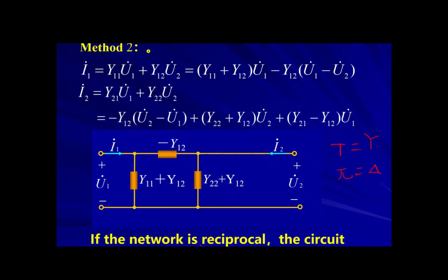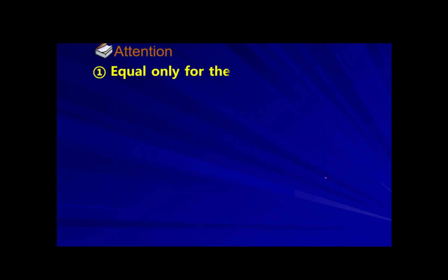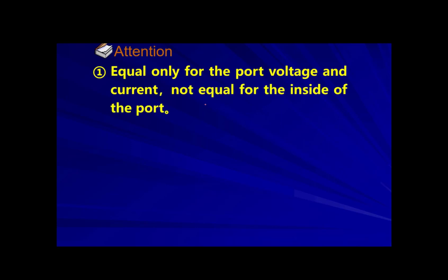Pay attention, the reciprocal circuit will be the delta circuit. The reciprocal circuit can also be expressed by the T circuit or the Y circuit. Pay attention, the equivalence holds only for the port voltage and the port current, not for the inside of the port.